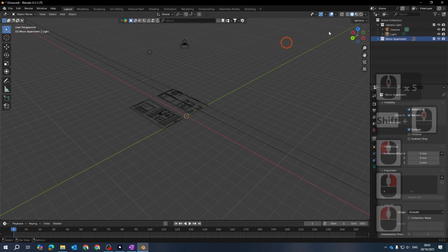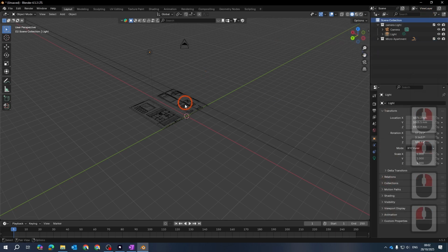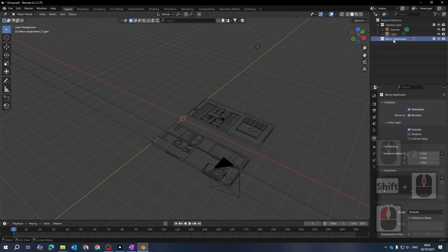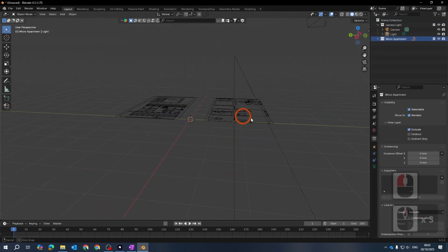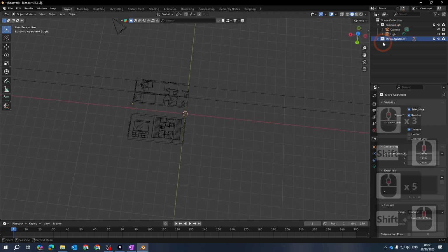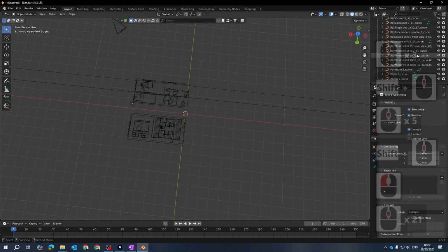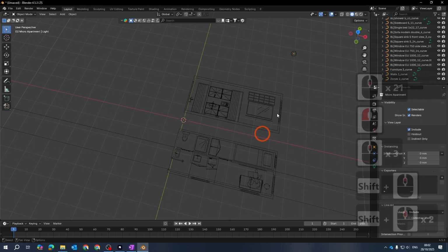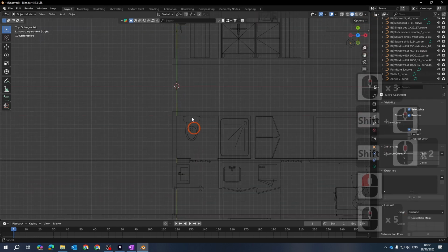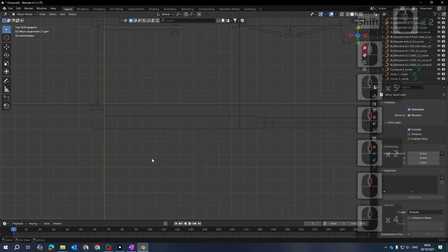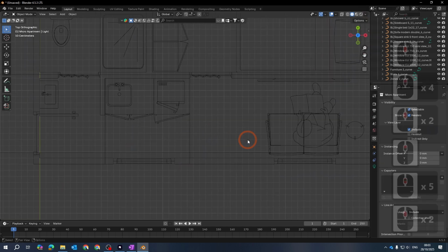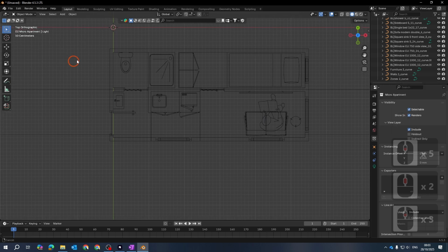Okay, you should see that this will try and import all of this information in a container. So these are containers, by the way. In the scene, you can make new containers, and I'll discuss that in a minute when we start modeling more information. But you'll see that it's brought everything in as different lines. Okay, so we don't need the line thickness, we don't need the text. So if we go to top view, the best workflow you should adopt is to try and measure something that we know, so that we know that this is to scale.